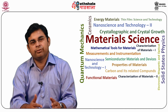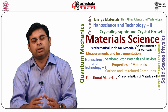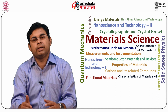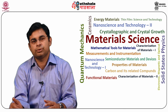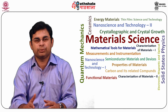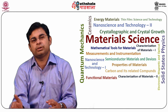The force F brings a change in the thickness of the crystal by delta t in meters, where F = (A × E / t) × delta t newtons. This is equation 2, where A is the area of crystal in meter square, E is the Young's modulus of elasticity, and t is the thickness of the crystal.